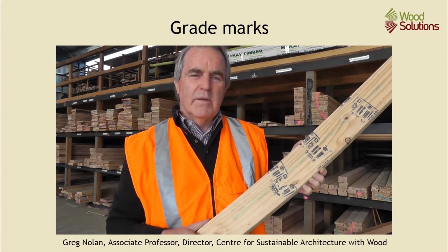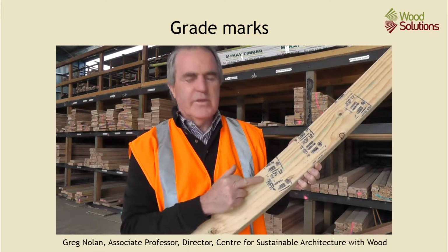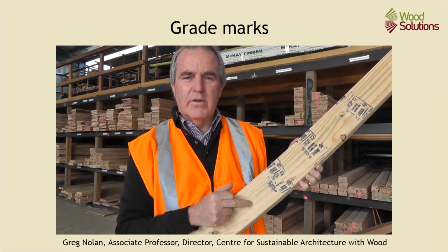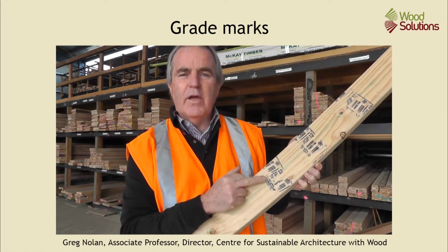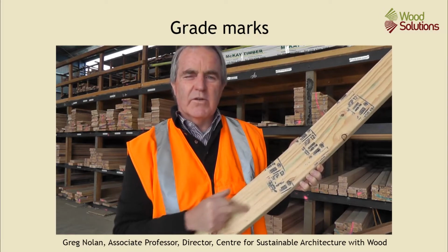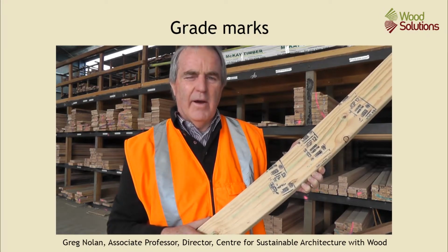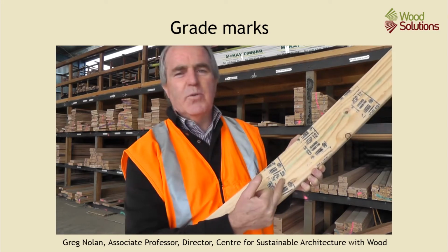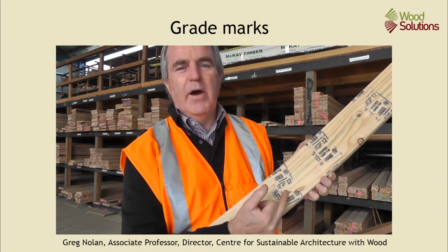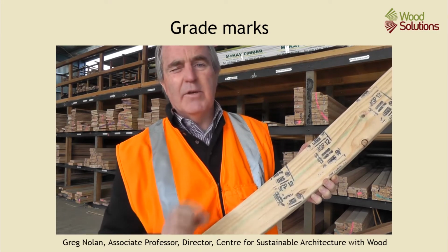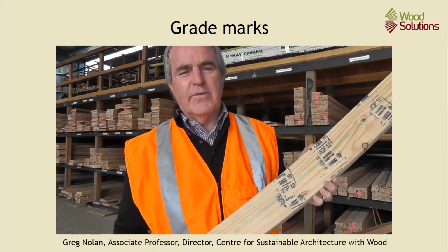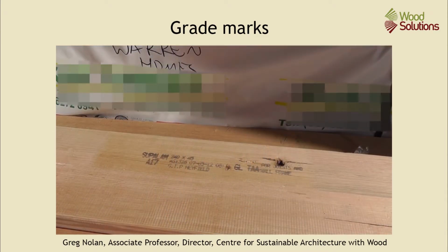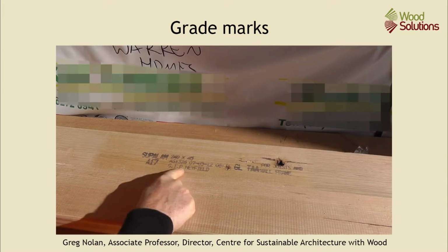But if you're using timber, the main thing you want to know is what the stress grade is and where you can use it. So you're going to be looking for these particular types of stress grades on the timber that you buy. MGP 12 is machine graded pine, and it has a number 12 to identify a whole series of characteristics.